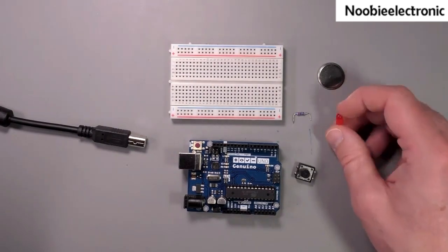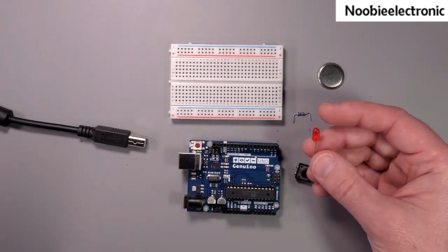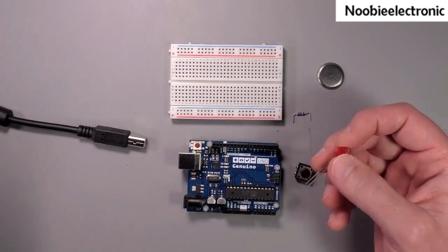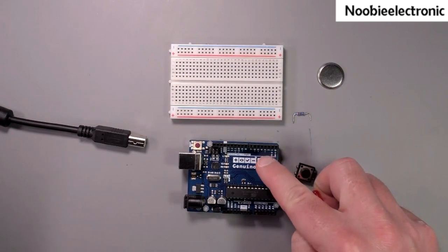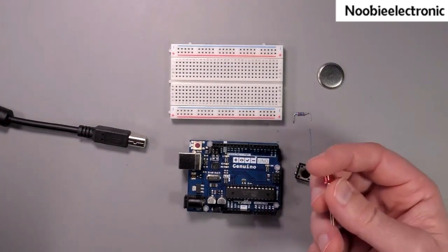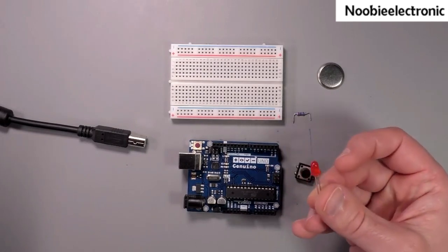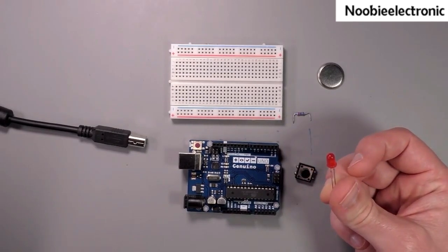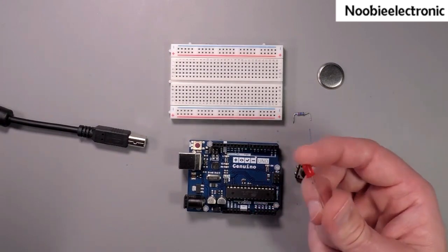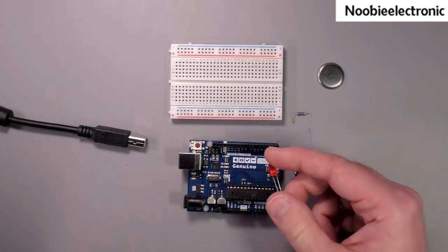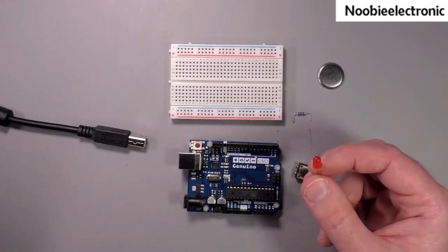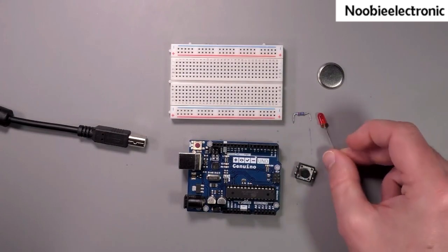Similarly with an LED. If you want to control the state of the LED to be able to turn it on and off, then you can connect the LED to one of the digital pins, configure the pin as an output. It's an output because we're trying to alter the state of a connected device, and then programmatically write a 5-volt value to that output, and that will have, as a result, the LED lighting up.